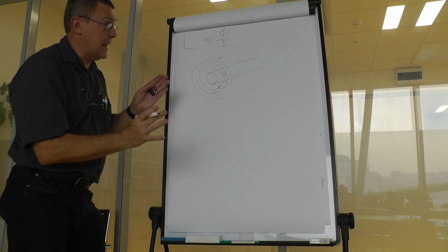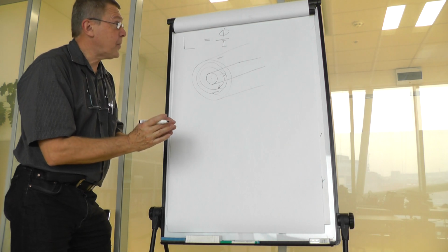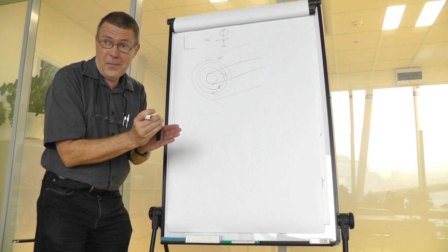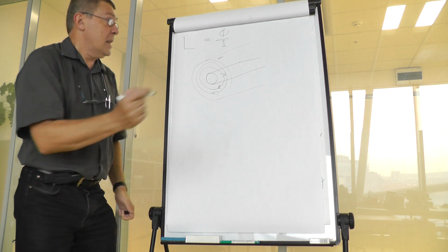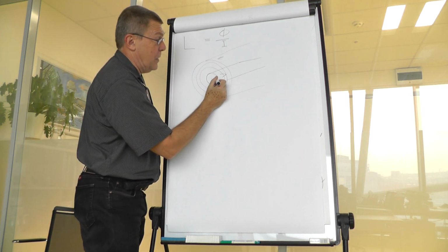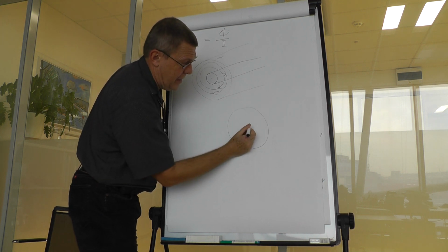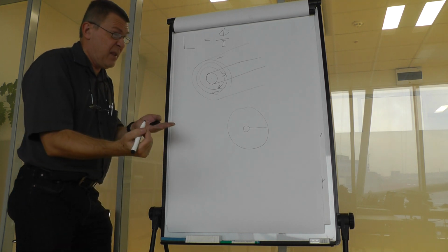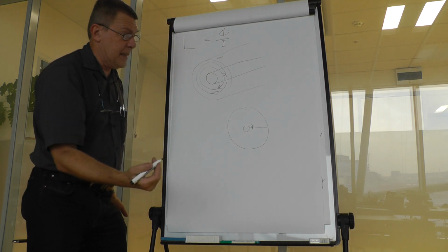And in order to find its flux, we would have to get an integral of flux density over a proper surface. Now, the simplest way to find out the surface is a radial section from the inner conductor to the outer conductor. Why a radial one? Well, first, all the flux lines are perpendicular here, so you will find it easily.